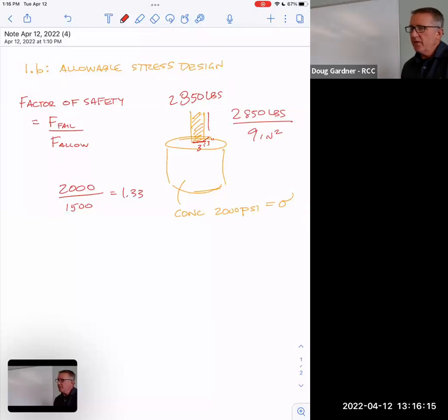A lot of times the two factors of safety that I see all the time, and I mentioned this to you before, but 1.5 is basically typical. And 2 is typical for stuff that is, what's the word for this? Civil. What civil really means is like stuff everybody uses, bridges, things like that. So you always have a 1.5 for a factor of safety. And it may even be double. So if it was double, then the limit would be set at 1,000. Does that make sense? So you're always bumping that kind of stuff in.